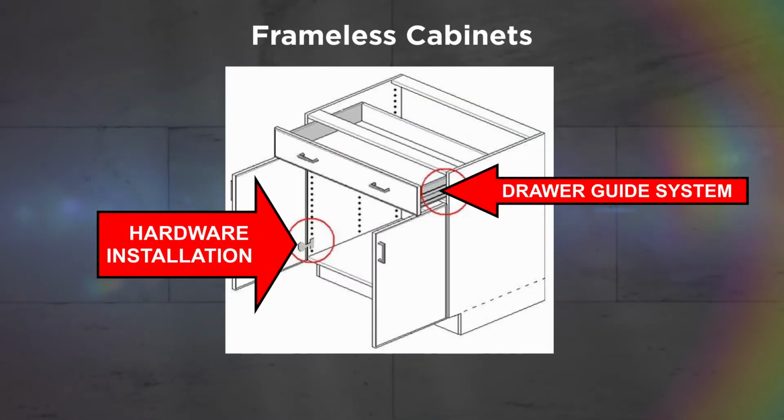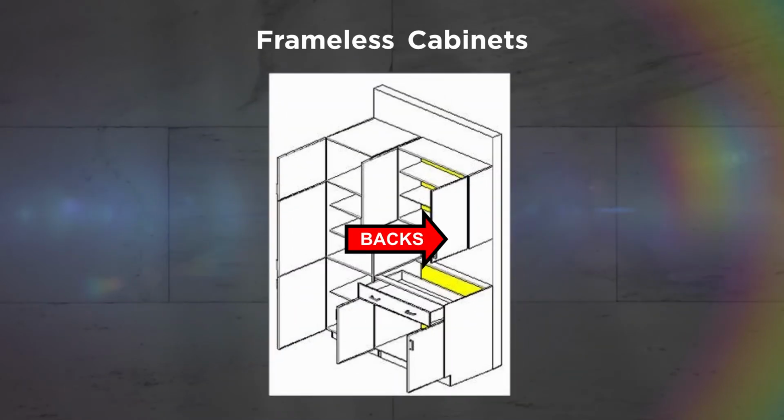Drawers for framed and frameless cabinets are typically made of solid wood or engineered wood. However, some frameless cabinet manufacturers incorporate a metal drawer side that includes the drawer guide. Also, note how the door hardware is attached to the 32mm spaced holes in the side panel of the cabinet. The shelf clip for a half-depth or full-depth center shelf can be placed in the same holes as the door hardware. The backs of frameless cabinets can be relatively thin because they offer no real structural support.